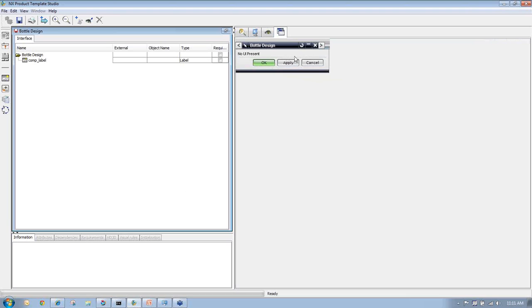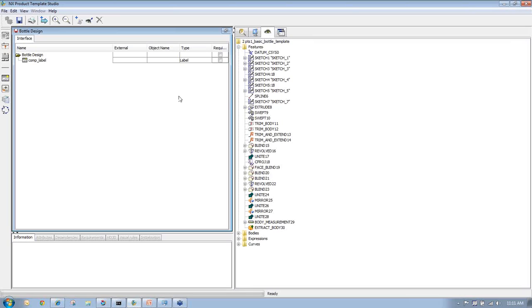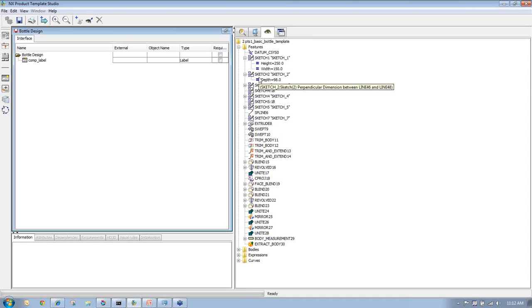You can see here, this is a standard dialog box that you would see inside of NX. Any screen that you bring up, any item that you're going to have to build, you would have your dialog box, call it, on the side there. You click on this other button over here. Now we start to see how this product was built. So being the designer of this and building a little bit of logic into a traditional part, I put in our height, width, and depth in there. While I'm building the process, maybe I didn't put that in there. Definitely add it.